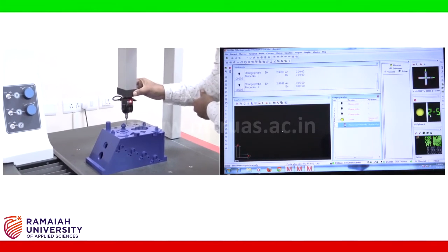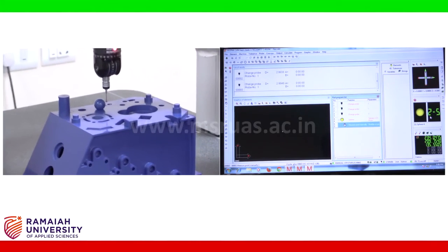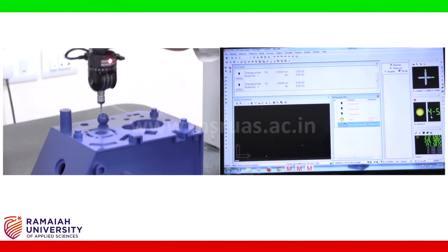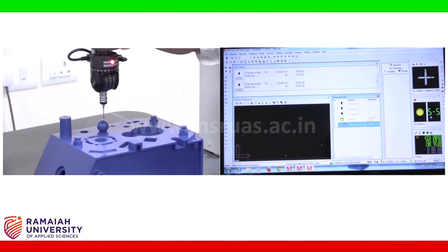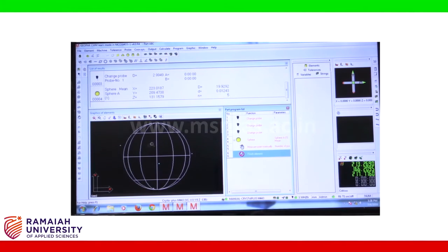So first point contact is completed. Next, the second point contact is awaited. Second is completed. Third point is completed. Fourth point is pending. Fourth point is completed, and the fifth point is expected. Now you can see the sphere geometry is being generated on the graphics window here, and you can see also the diameter of the sphere. You can see diameter is 19.9292 and number of points are 5.